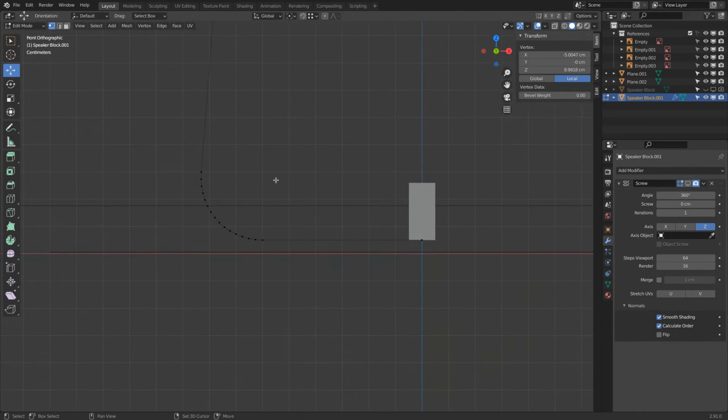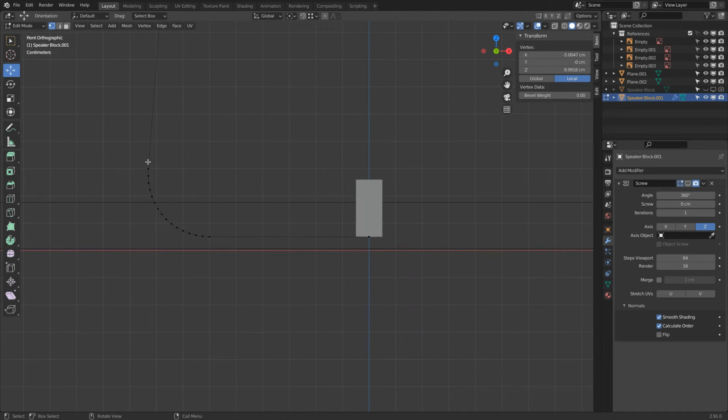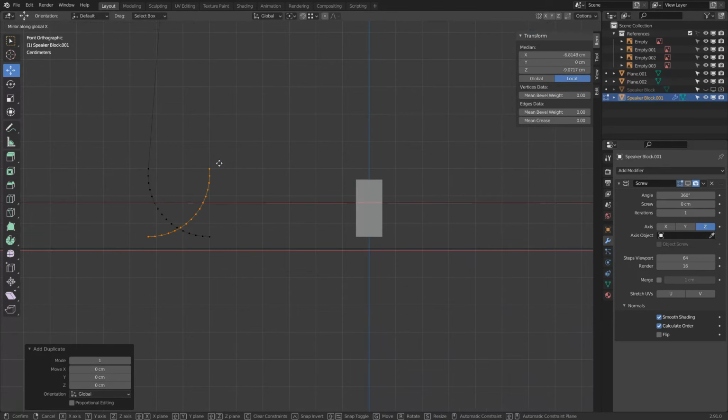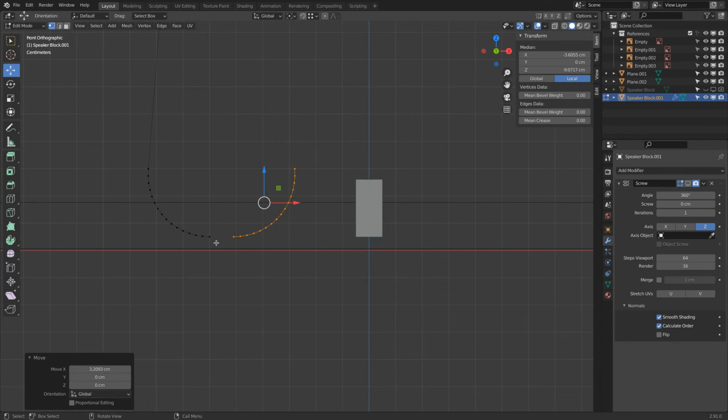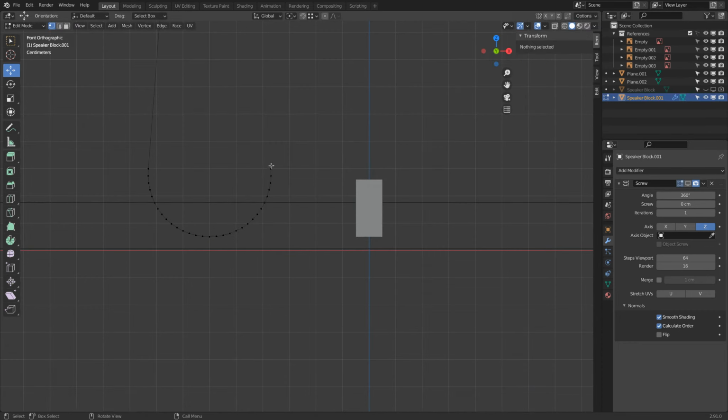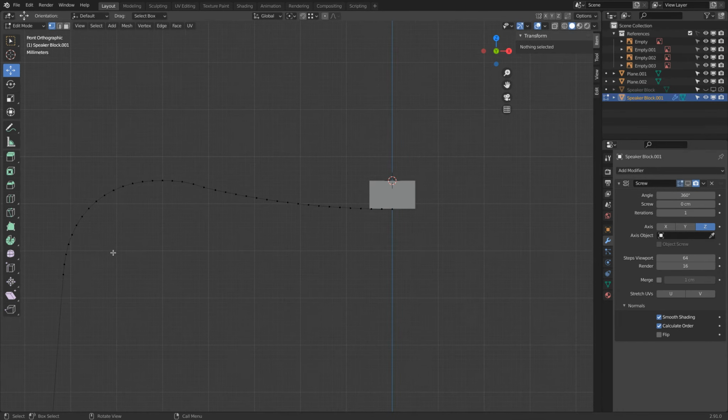Let's go back to here. Because we made this bevel with a 0.5, which is a true quarter arc or tangent. When we delete this point, select this with B, Shift T, Escape, Control M, X, bring this over, G, X, and snap. You see that this is now really a circle.